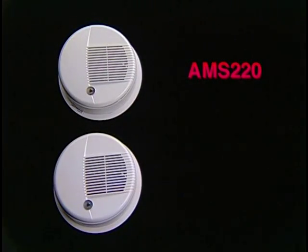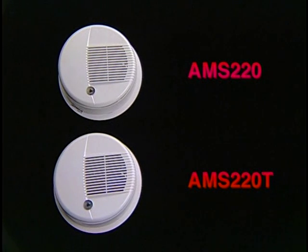Addressable smoke detectors, the AMS 220 or AMS 220T with optional heat, can be used in commercial fire applications. Addressable smoke detectors can be programmed as either standard or auto-verify fire zones.